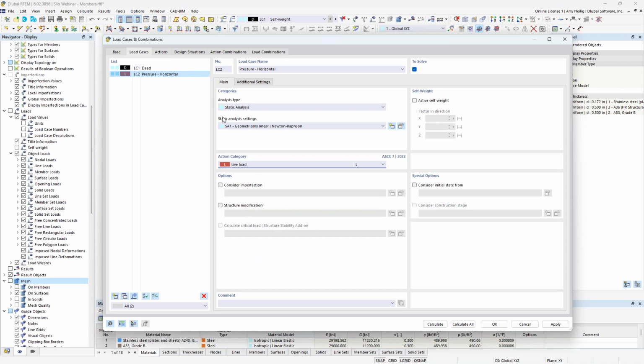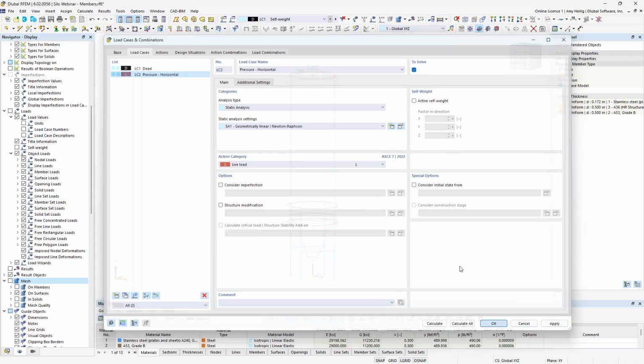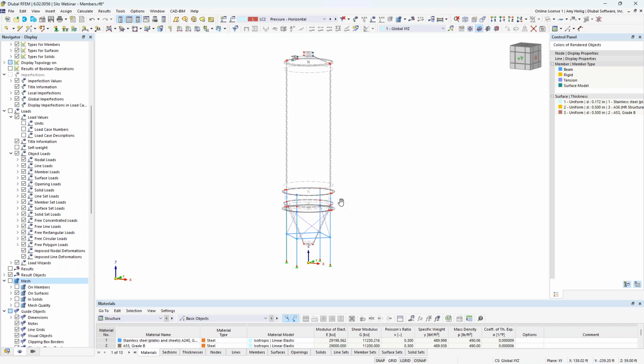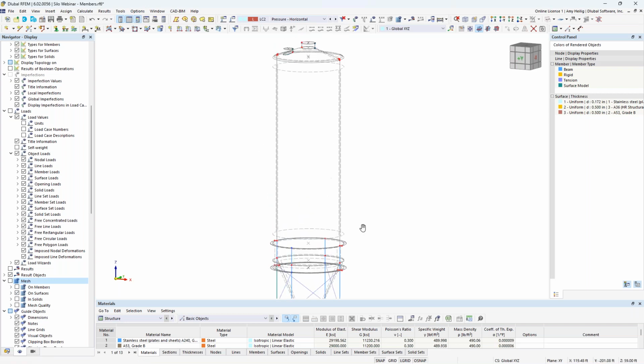So now that I've generated this load case, I click OK, and I'm back here within the program, but notice load case 2 is selected within my drop-down box. Now with this fill load, I am going to assume that I'm not going to fill it up to the full height of the silo walls, up to the very top here, but rather we know this fill will be at a maximum a couple feet below the top of the surface.